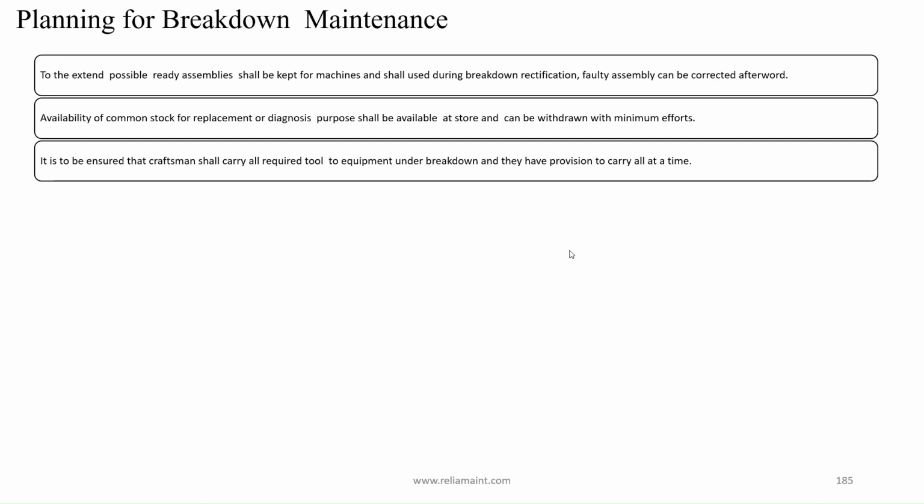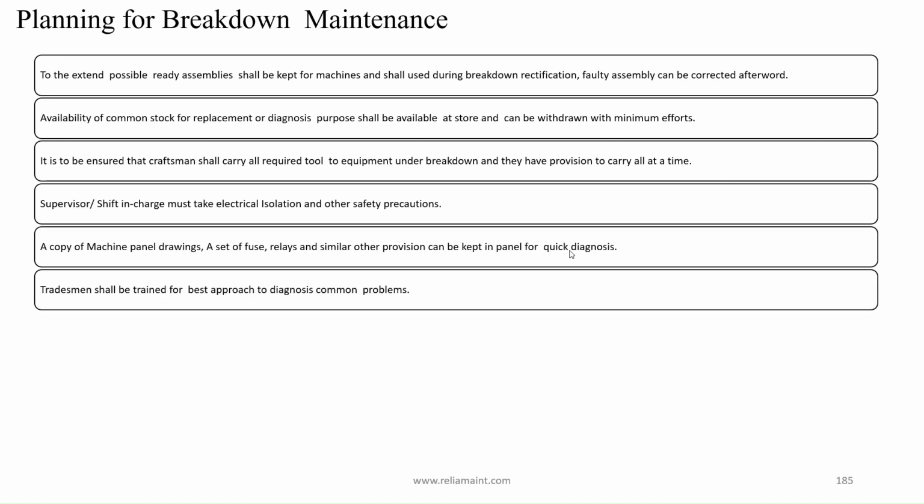Supervisor or shift in charge must take electrical isolation and other safety precautions. A copy of machine panel drawings, a set of fuses, relays, and similar other provisions can be kept in the panel for quick diagnosis. Tradesmen shall be trained for the best approach to diagnose common problems. A machine operator with fair knowledge of equipment mechanisms can serve as a good resource for fault diagnosis. Maintainers shall share knowledge with operators.